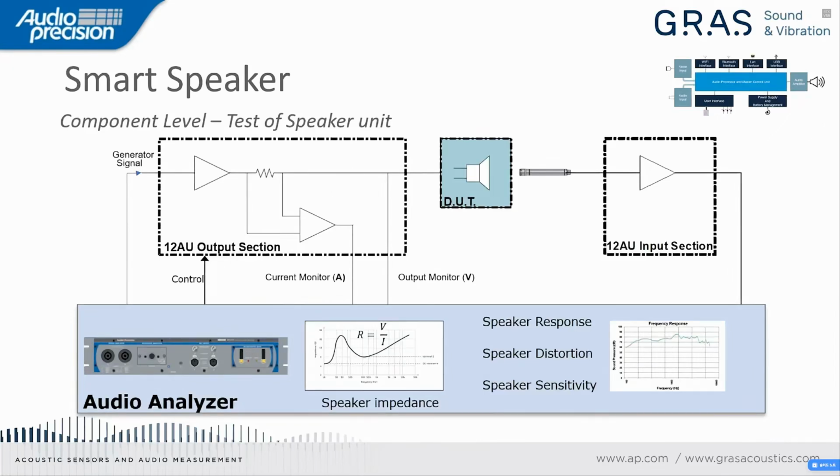We can also do a test at component level. In this case, it is a test of the speaker unit itself. With the speaker unit itself, we are of course interested in frequency response, distortion, and sensitivity of the speaker.